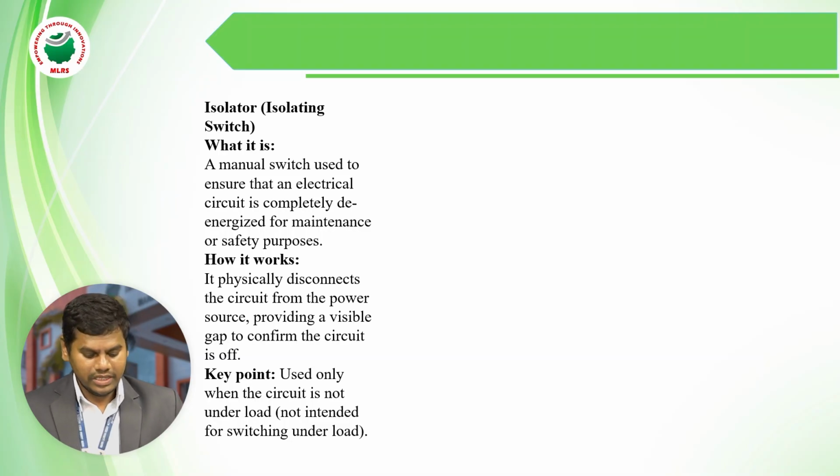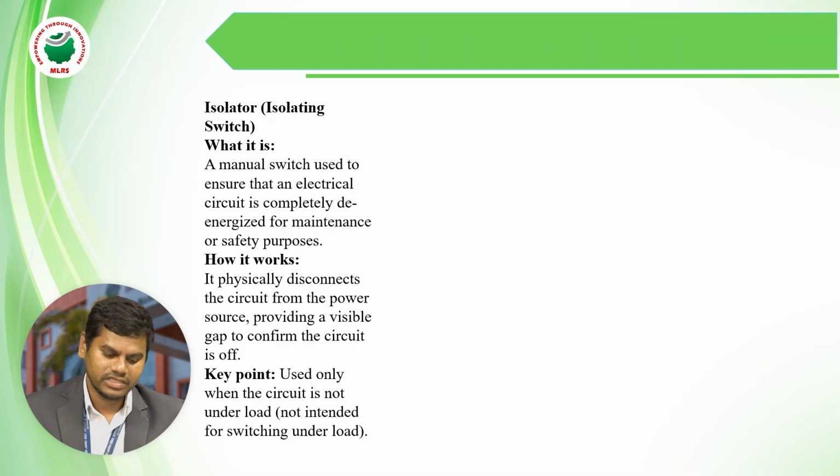The key point of this isolator or isolating switch is that it is used only when the circuit is not under load condition. It is not intended for switching under load.